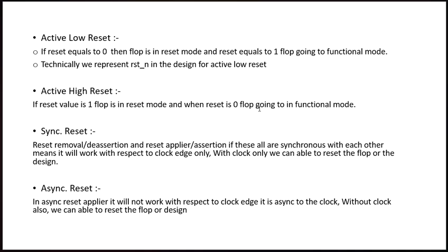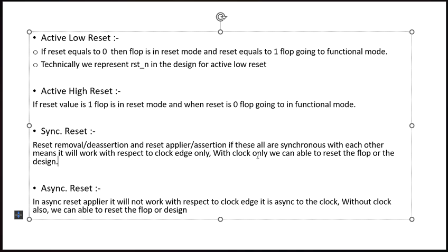So what is meant by synchronous reset and asynchronous reset? We already learned about reset removal, or deassertion, and reset apply, or assertion. In synchronous reset, if the reset removal or deassertion and the reset apply or assertion are synchronous with each other, meaning it works with respect to the clock edge only, then it is called synchronous reset. Only with the clock can we reset the design. In my design, suppose there is no clock, then I am unable to reset things in synchronous reset.